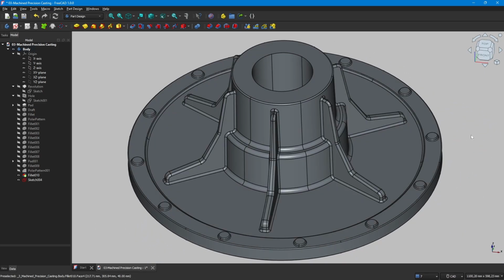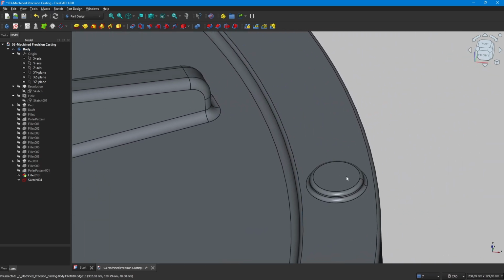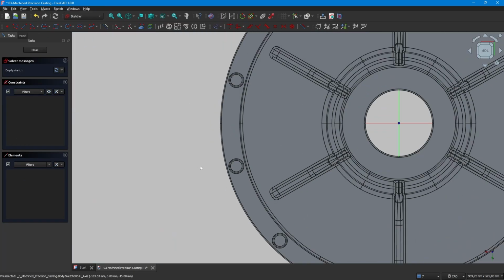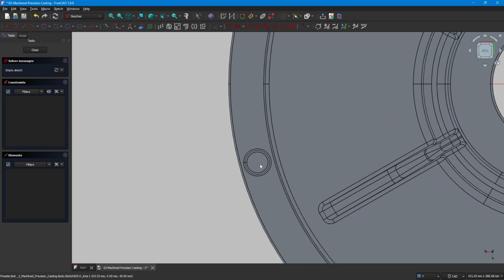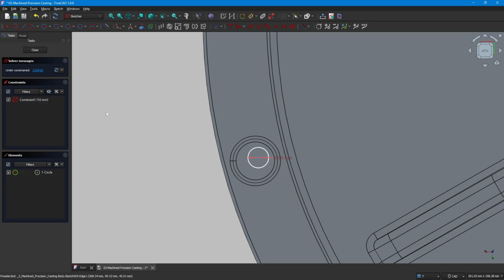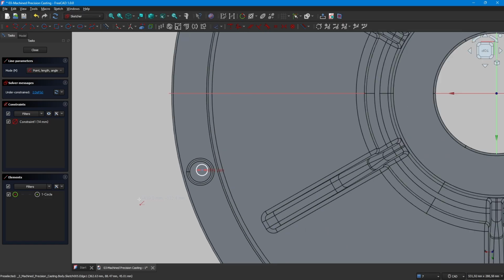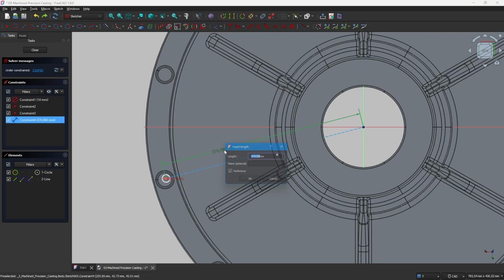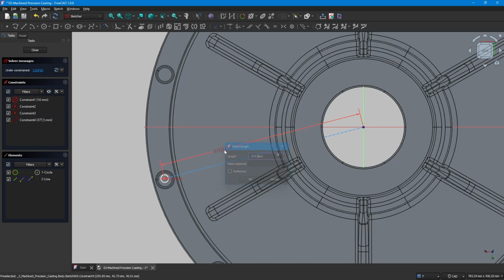Okay, wonderful. Let's continue with the holes for the M12 screws on these pads here. We need another sketch. Okay, let's use, no, we don't use the radius edge, we make a new circle here. Should be 14, the diameter. And we have a distance to the center of 377.5. And we have an angle of 15 degrees.